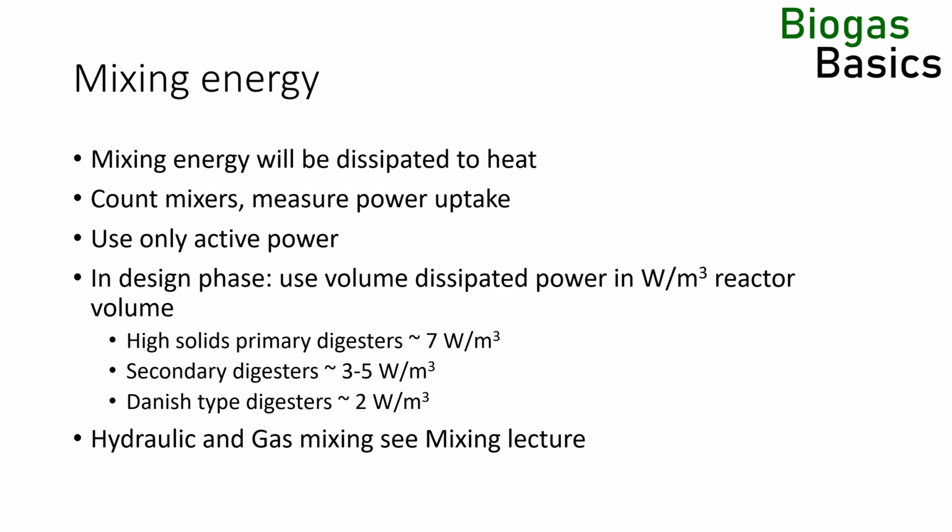If you use gas or hydraulic mixing, the approach is similar. For hydraulic mixing, calculate the kinetic energy of the flow exiting the nozzle. For gas mixing, take the enthalpy into account. Gas mixing will convert a substantial amount of the compressor energy straight to heat and not into kinetic energy. I will do a mixing presentation, where I will talk about this in more detail.